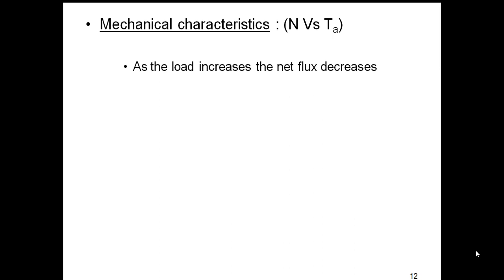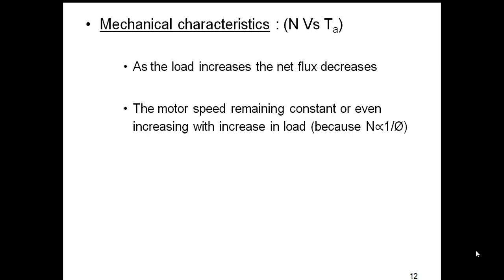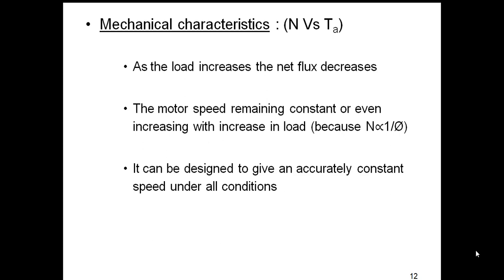And here when the load increases, we know that the net flux gets decreased, so the motor speed remains constant, or even increases with increase in the load, because the speed N is inversely proportional to the flux phi.